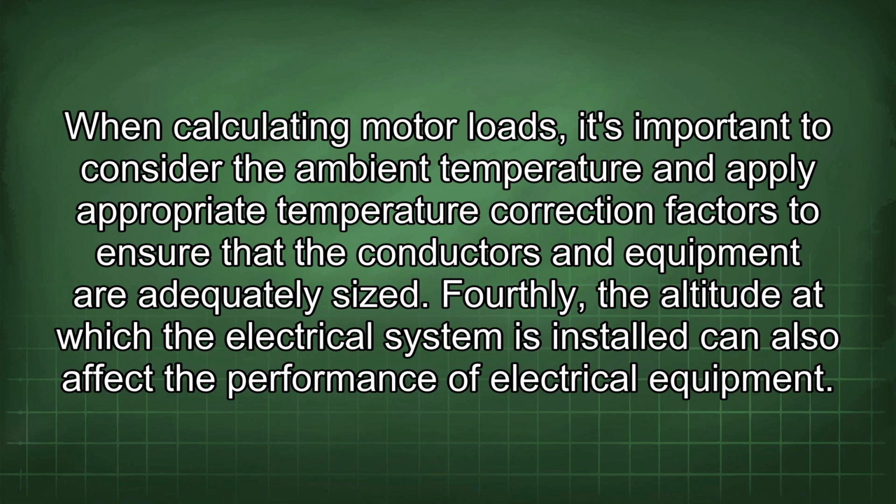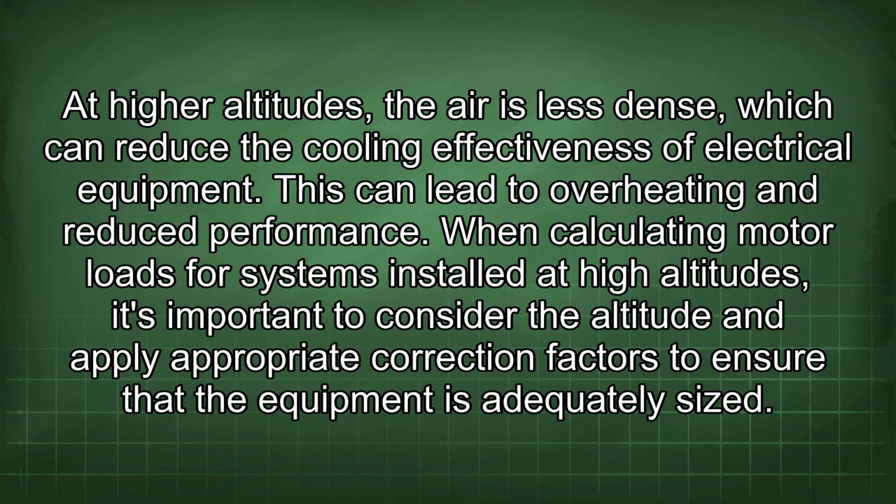Fourthly, the altitude at which the electrical system is installed can also affect the performance of electrical equipment. At higher altitudes, the air is less dense, which can reduce the cooling effectiveness of electrical equipment. This can lead to overheating and reduced performance. When calculating motor loads for systems installed at high altitudes, it's important to consider the altitude and apply appropriate correction factors to ensure that the equipment is adequately sized.